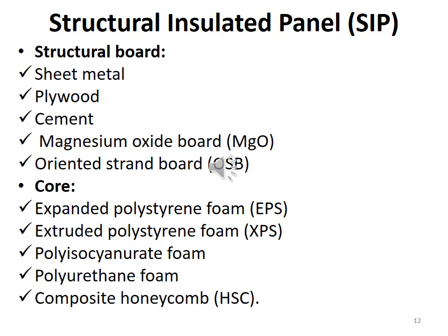To maintain the higher insulation values through the spline, manufacturers use insulated lumber, composite spline or mechanical lock, overlapping OSB panels, or other different useful methods that can be much fruitful for the production and the fabrication of structural insulated panels.